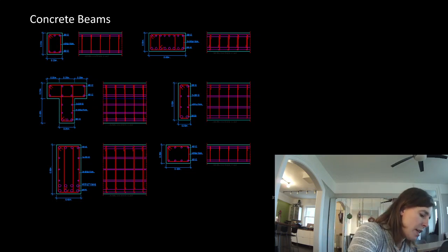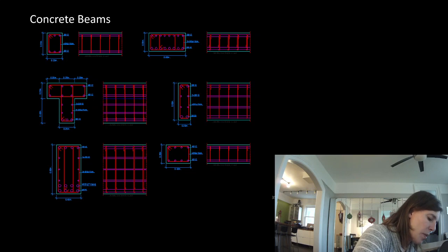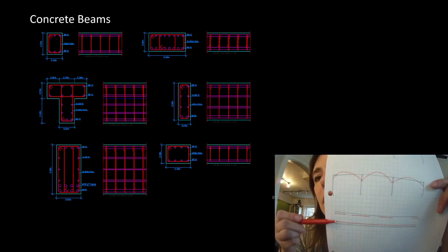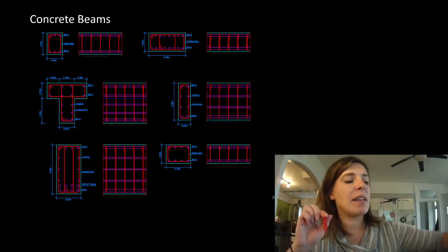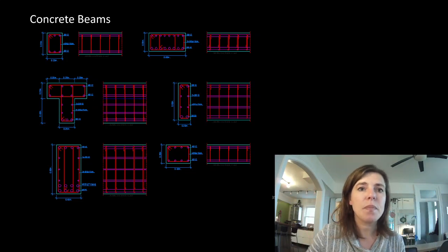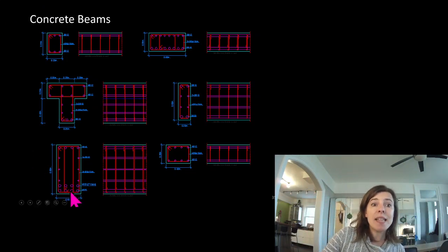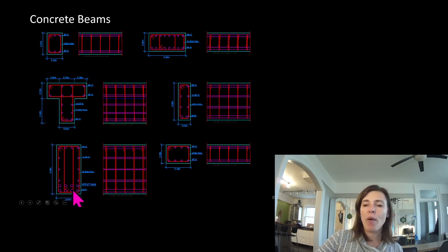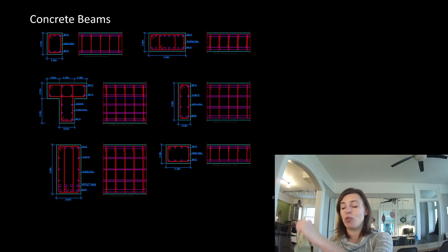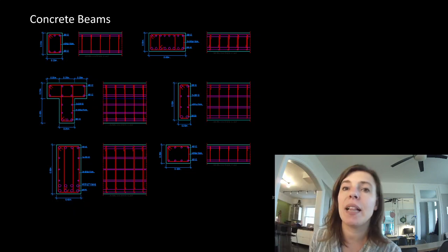Often, if this was a beam, we would design it so that we have continuous bottom steel, and we might only have top steel where we needed it designed for the reverse bending. You can see that if it's really working hard, we might need 2 layers of steel down here. You can imagine that makes that stress profile diagram look a little more complicated, because now the arrow is somewhere in the middle of those, or the centroid of our tension elements.